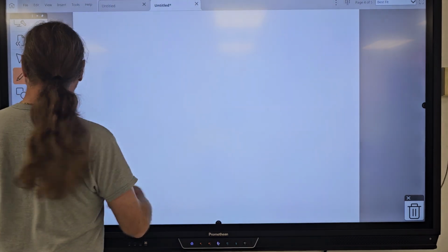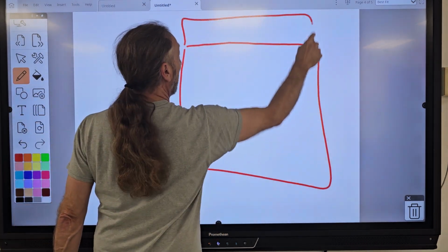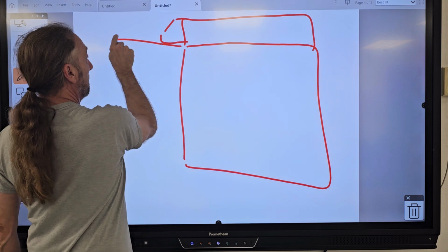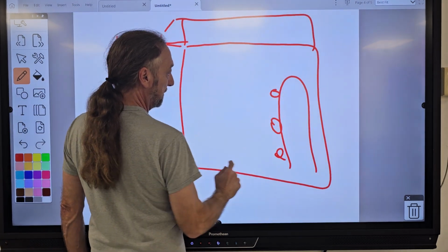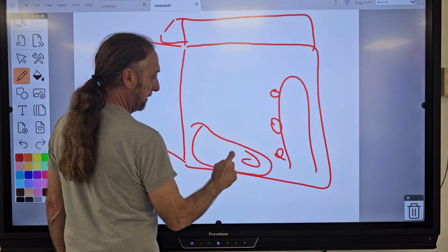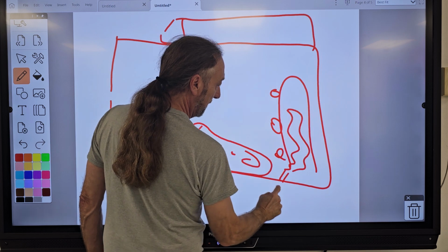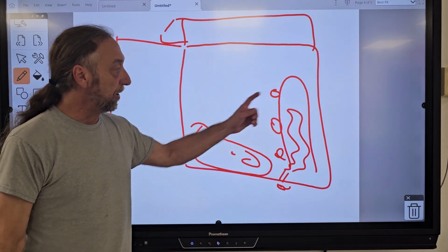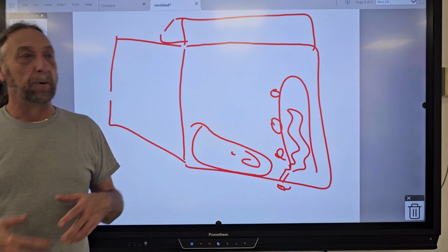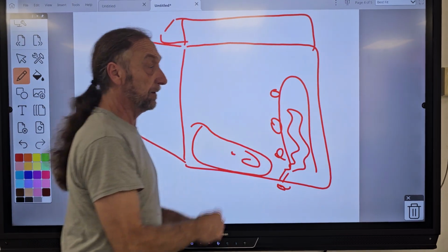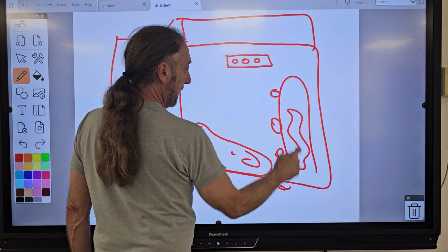Let's do that dryer drawing I had again. Here's your control panel up here, the heat element, your thermostats, your blower housing, and the thermostat right here. And you go right here on the 2 heater wires, and you got 0 volts. Well, it could be all these parts, it could be a timer, it could be a centrifugal switch on the motor. But instead of starting to test everything, I go right back here,